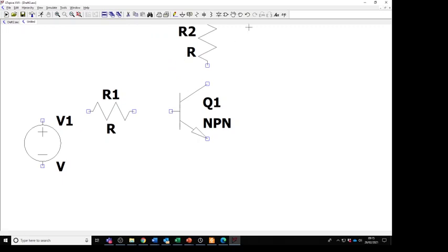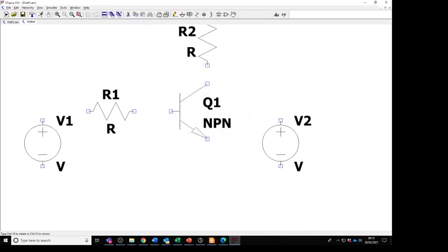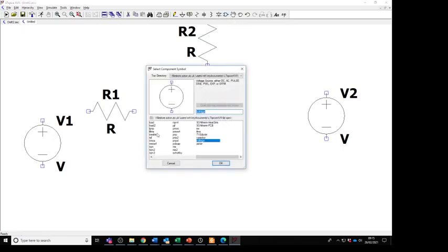We're going to need another voltage source. Right. So put that one over there. So we can pick up a voltage source, and we're going to use it as our power supply. If we want to emphasize that it's a power supply, and just for neatness of diagrams, we can actually go to a different library. It takes a bit of digging around normally to find it. So these are all the libraries we can get. So I think if we go to MISC for miscellaneous, it picks up all kinds of other things, and we can pick up things like battery or cell, which is half a sort of a battery, if we want to have different symbols.